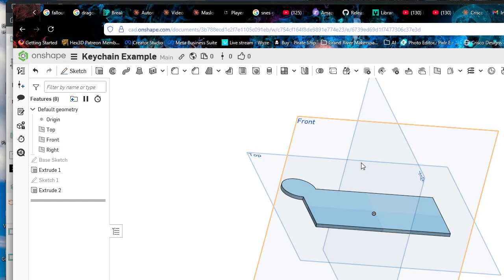So like Bill, I noticed with your film spool thing that you had, everything was blue on that sucker. All the sketch was blue. So the first thing I would do would be going in and basically you want to make as much black and defined as possible. Why was it all blue? Because it wasn't defined, or some parts of it weren't defined. My guess is you did a pattern for those. Yeah, I did hubs, a sixth of it, and then I rotated it around.